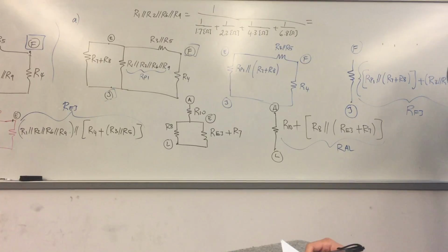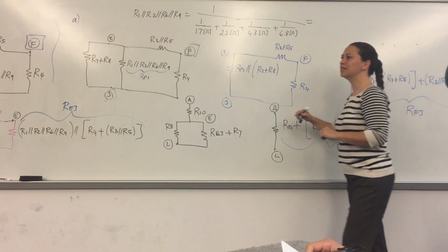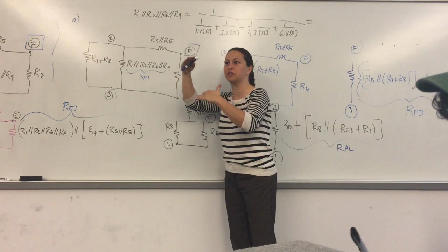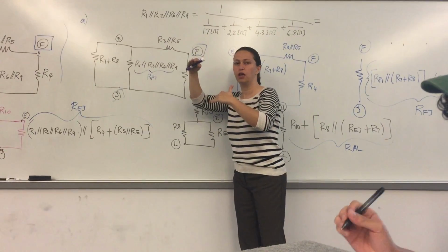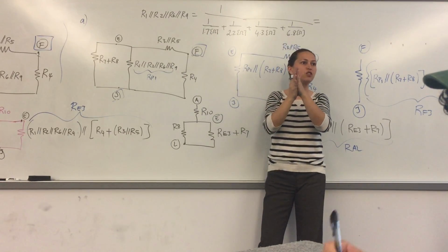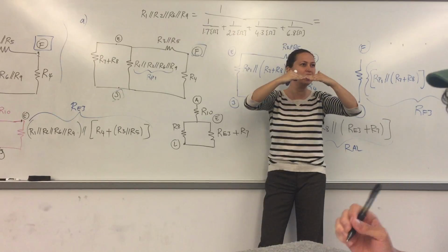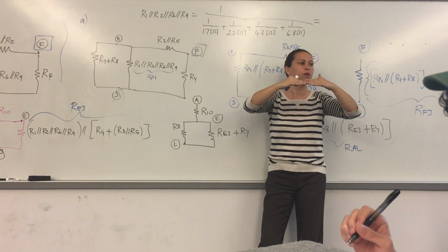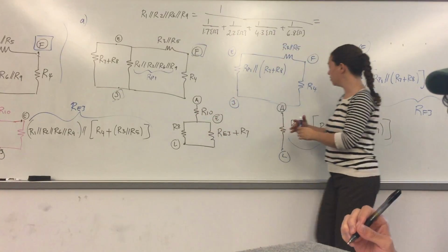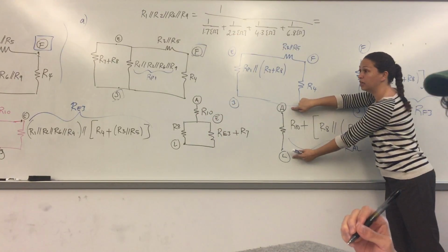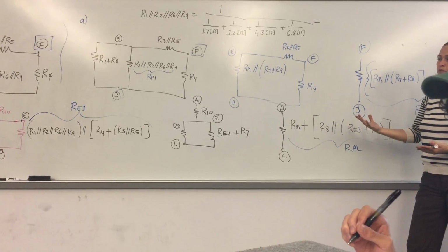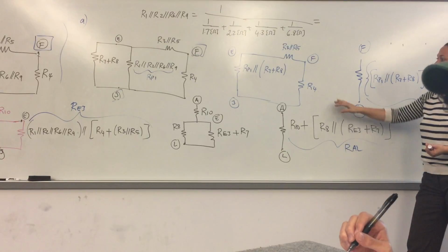Okay? It's not a big deal when you're doing the parallel combinations, because parallel combinations keep the nodes, right? No node is lost when you combine two resistors in parallel. But when they're in series, then you have to be careful. That's how you get rid of each and every node one by one, and then you arrive. The goal is to arrive at only those two nodes left, whichever you are interested in. So we conclude that R4 is parallel with J and F.